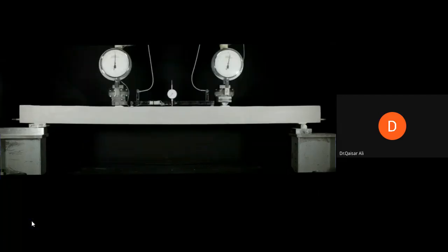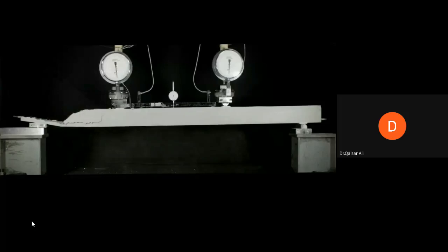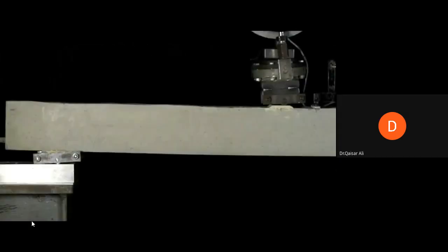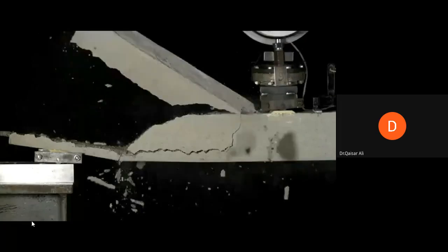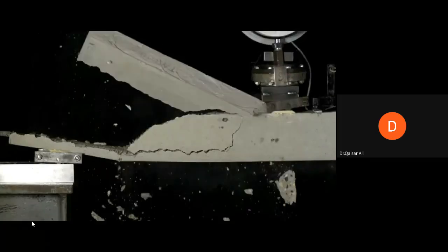Starting to apply vertical loads to the specimen, and the beam starts to deflect. Then quite suddenly, we have an explosive failure near a support. This is what we call a shear failure, and it is something that we always want to avoid. If we slow down the footage, here is that failure again. Look how sudden it is. Now remember, this is a beam in which we have left out the shear reinforcement, and this is the consequence.